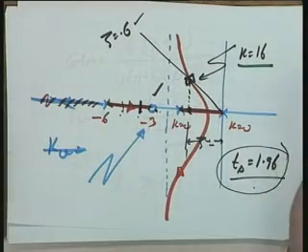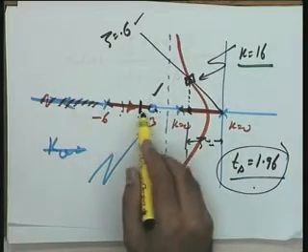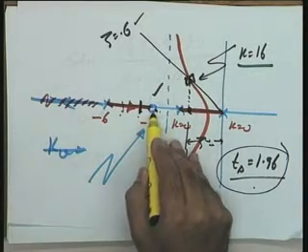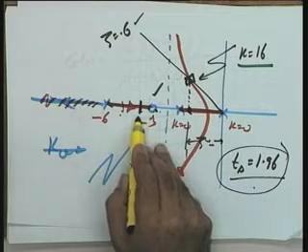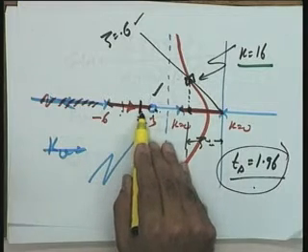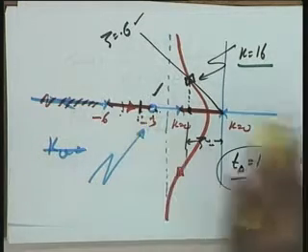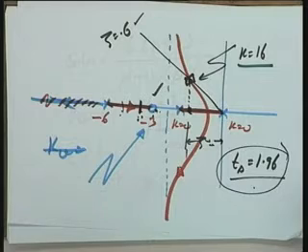So neither the effect of the zero nor the pole, but exact cancellation is not possible. They will be close by. So the peaking effect of the zero, as well as the effect of the pole in making the response sluggish, will get nullified. Nullified is just an ideal term. It will get reduced, yes, but by simulation you have to examine.